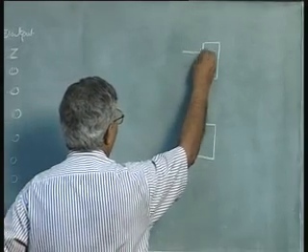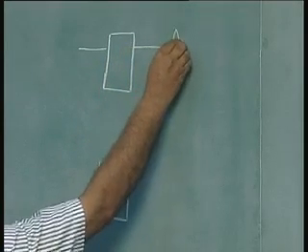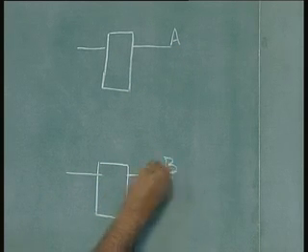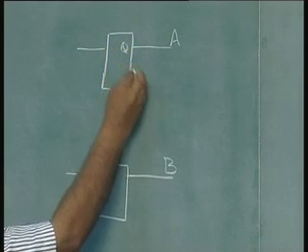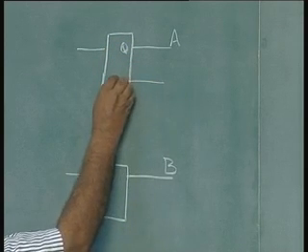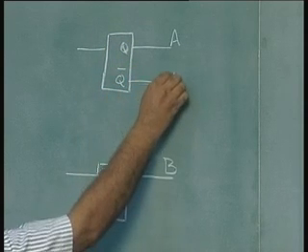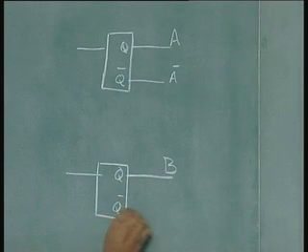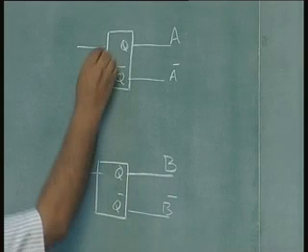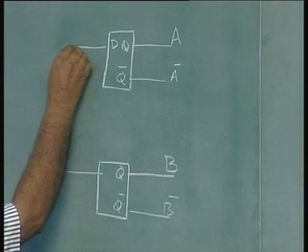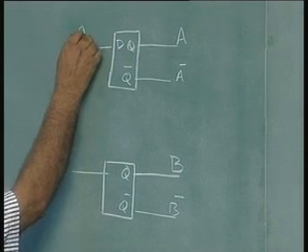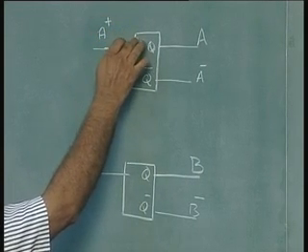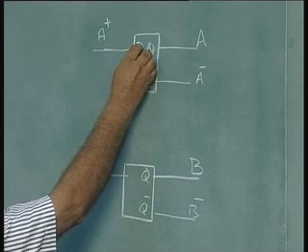So, this is flip flop A, output is A, flip flop B, B. So, Q is A, Q bar is A bar. Similarly, Q for this flip flop B, Q bar for B bar. The D of this flip flop we will call it DA or A plus. The next state information will be, for a D flip flop, the output follows the input.